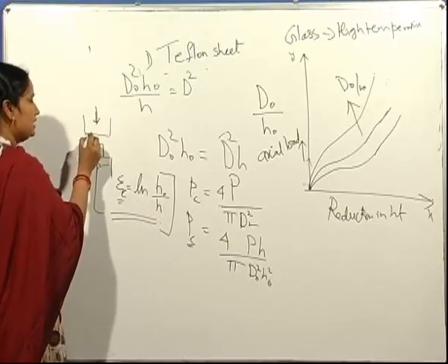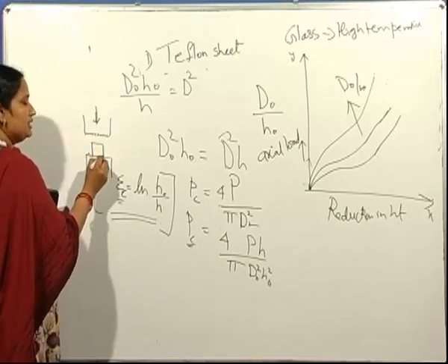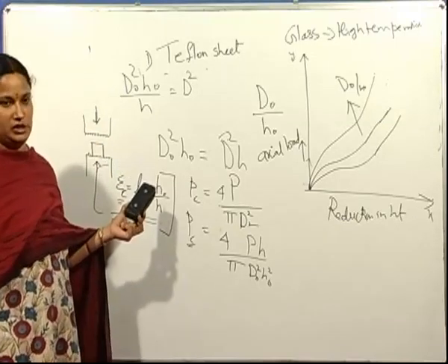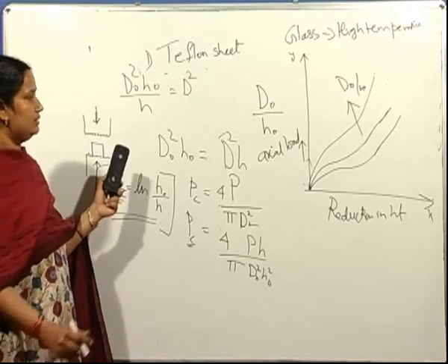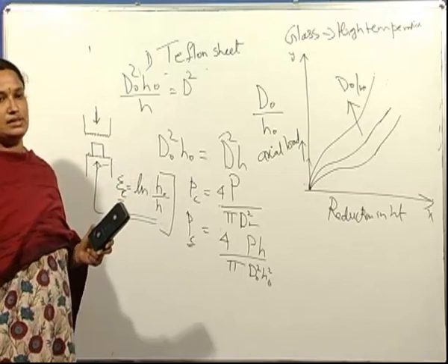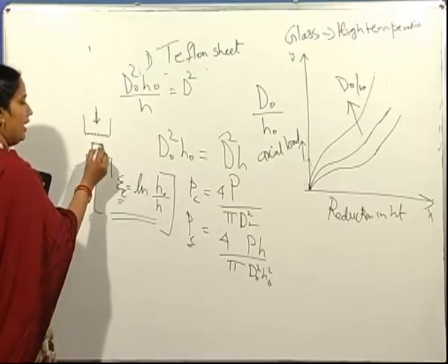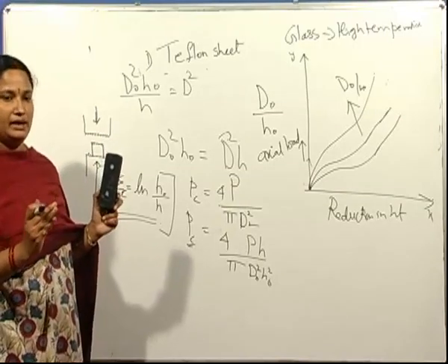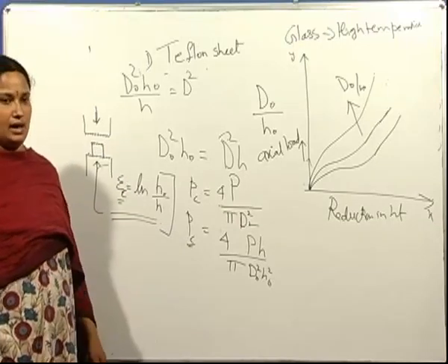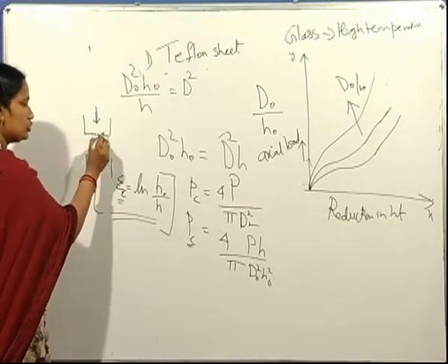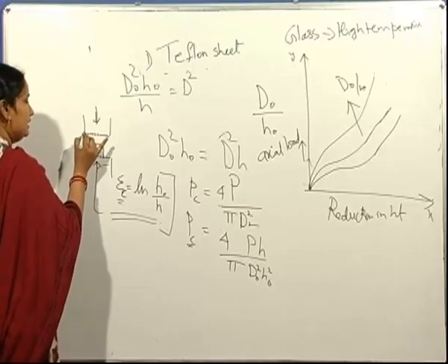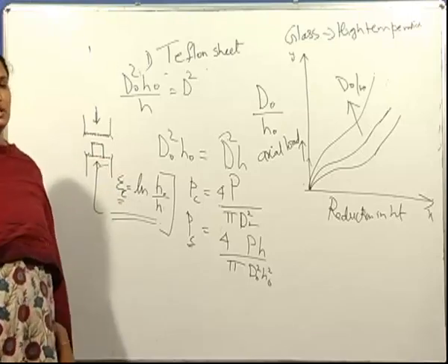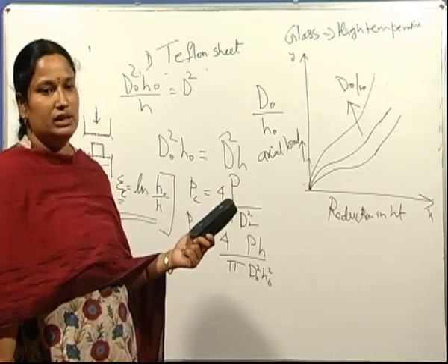So if these platens, they should be smooth and not rough, because if they are rough, it increases the friction. Once the friction increases, then barreling, bulging occurs, and the specimen at the surfaces do not undergo deformation, and only the specimen at the mid height undergoes deformation and the barreling occurs. Thereby the platens should be smooth, as well as slightly curved at the ends to retain the lubricant, such that the lubricant is not torn away during the deformation.